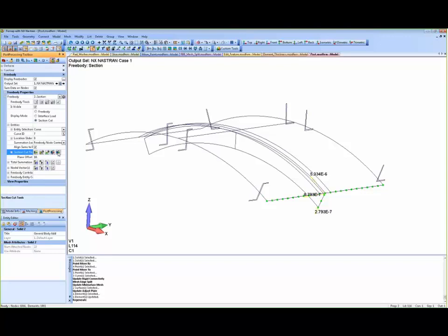And then these two buttons here are to actually slide through your curve. You can offset your section by a certain percentage of that curve in this case. And if I say move up 10%, see how it's moving along that curve, and the values are updating as I move. Another way to do that is using this little location slider button here, and I can grab it and move it along that curve as far as I want and get different outputs.